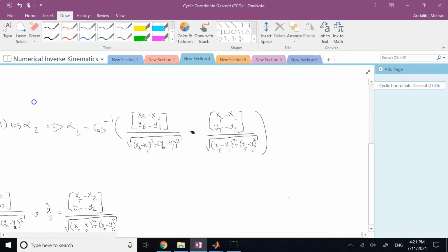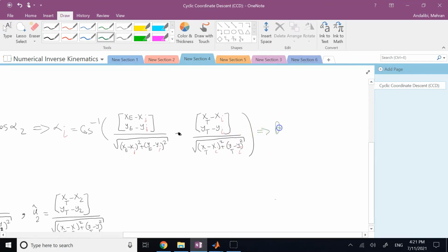So this is the update, and from here, each angle theta I is going to be whatever it was plus or minus alpha I. Now, I write it for you here: when changing the angle of joint I, you need to update the locations of the end effector and any joint J where J is bigger than I. Okay, so that's the important thing.